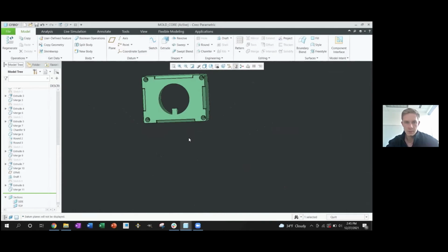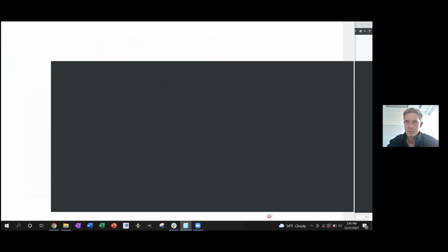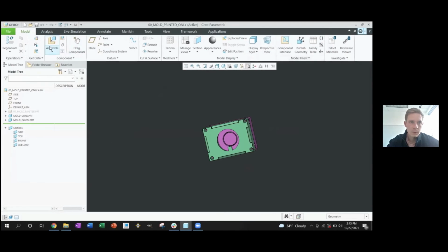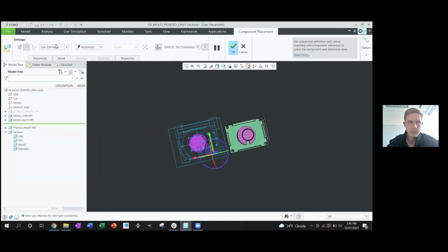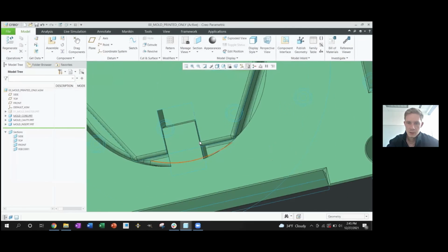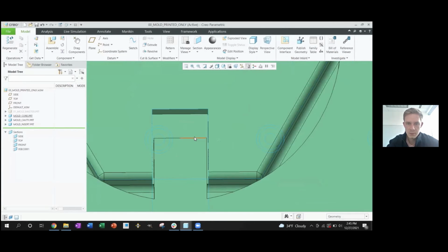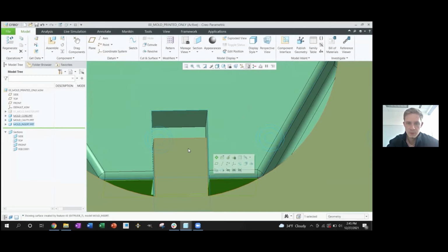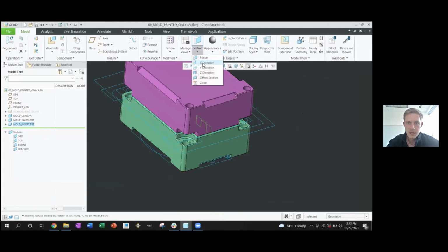Now that we've designed that, let's jump to our mold assembly. We'll make sure that we designed everything to spec. So we'll go ahead and assemble. We'll add this insert feature into our mold assembly, and since it's a copy of this mold block, we can use a default placement here. That's going to allow us to see there was a little mismatch here. We were using different faces for the length of this insert, but we can fix that in a moment.